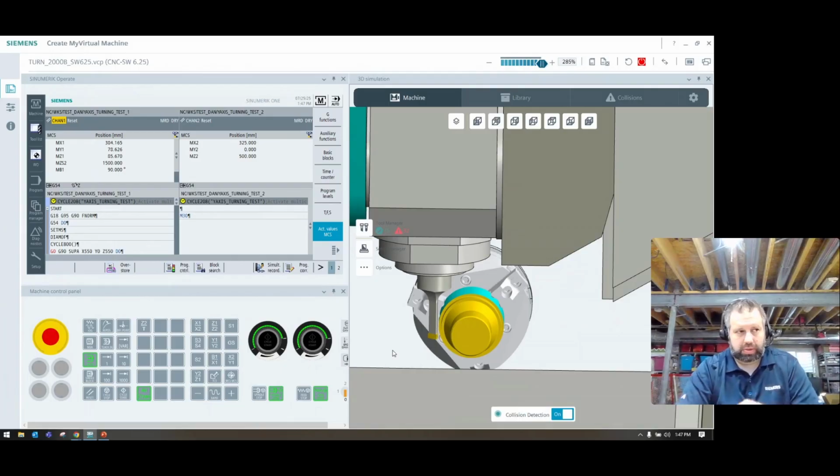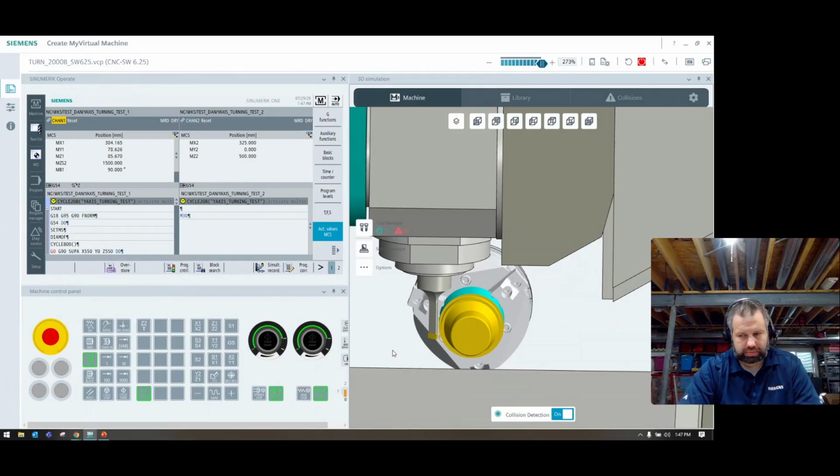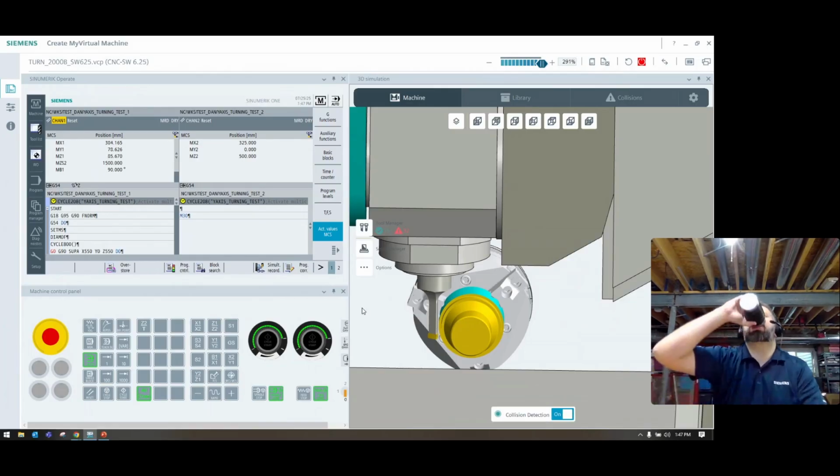Can the prime turning improve the surface finish of an ID sphere or spherical circle? I am not sure the answer to that question. I think that might be one to dive a little deeper into with Sandvik. I don't know either. Obviously, constant surface speed in my mind would have a bigger impact, right? Maintaining chip load.